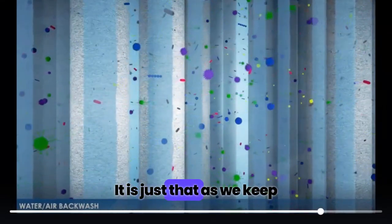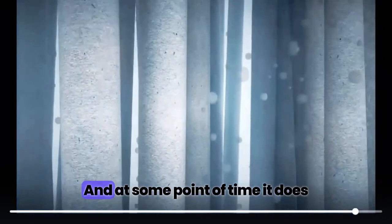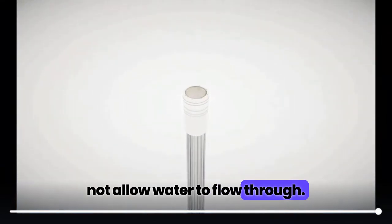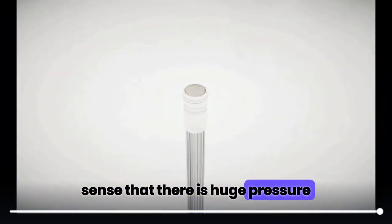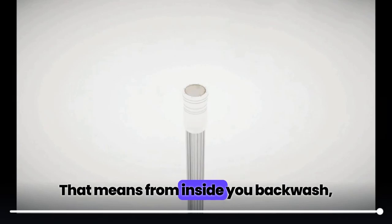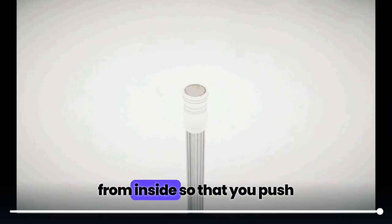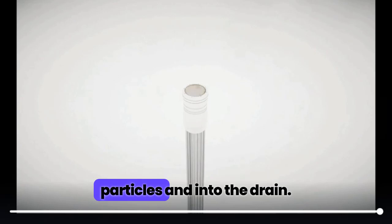It is just that as we keep on putting pressure, more and more physical impurities will get stuck on the membrane surface, and at some point of time, it does not allow water to flow through. At that point of time, a sensor will sense that there is huge pressure difference and reverse the flow. That means from inside, you backwash. You give water at a higher pressure from inside so that you push away the accumulated particles into the drain.